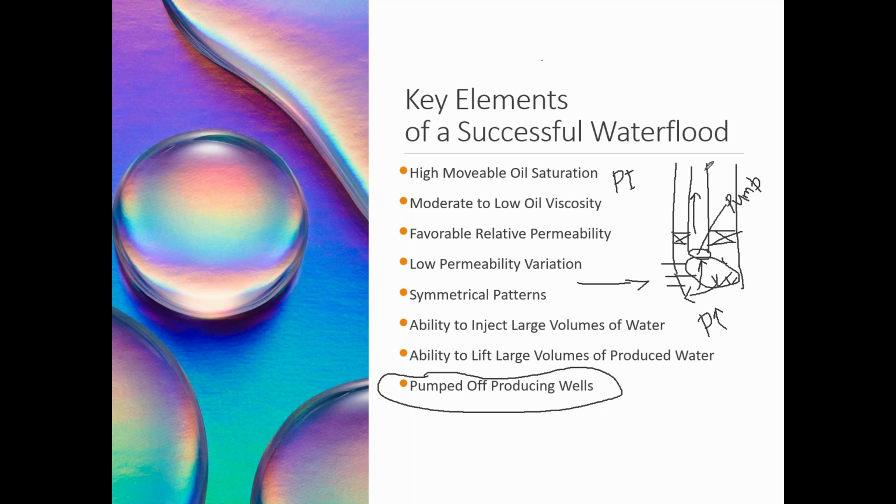So at the same time, when you are injecting water, you should also know that the water cut will be increasing in the producer wells, and you should have a sufficient mechanism by virtue of which you can pump off all the produced water.